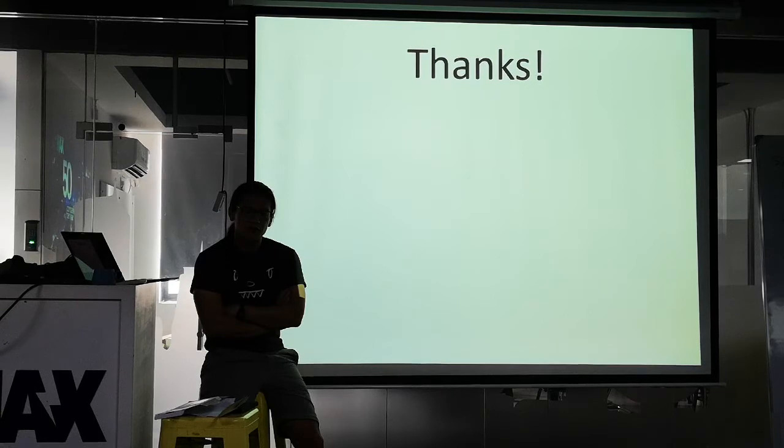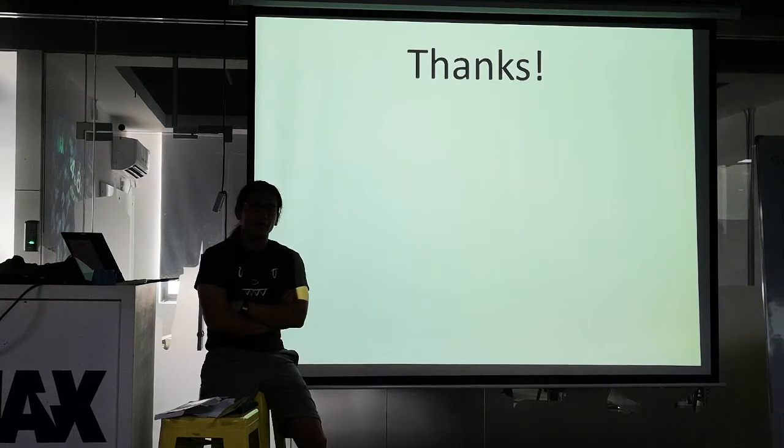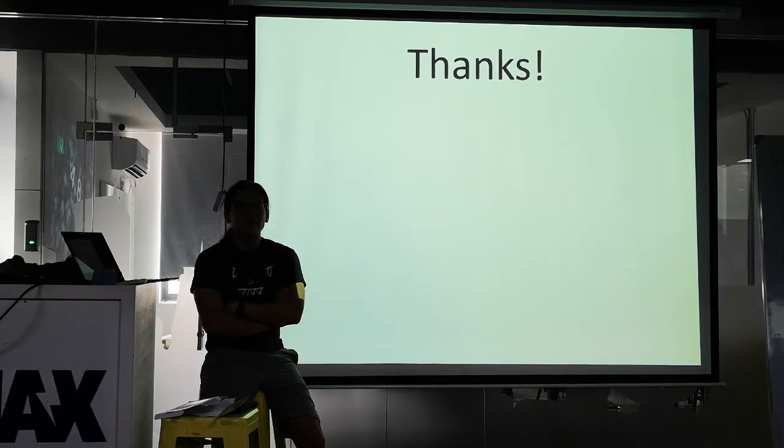I think your question is when do you start doing the ECO in the process? My rule of thumb is after you place a purchase order. If you're just in the quotation phase or prototyping and you haven't asked the factory to do anything, you don't. Whatever it is, it's in your head. Maybe the contract and payment differ after ECO or before ECO. Yeah, the ECO will affect the price that you pay.